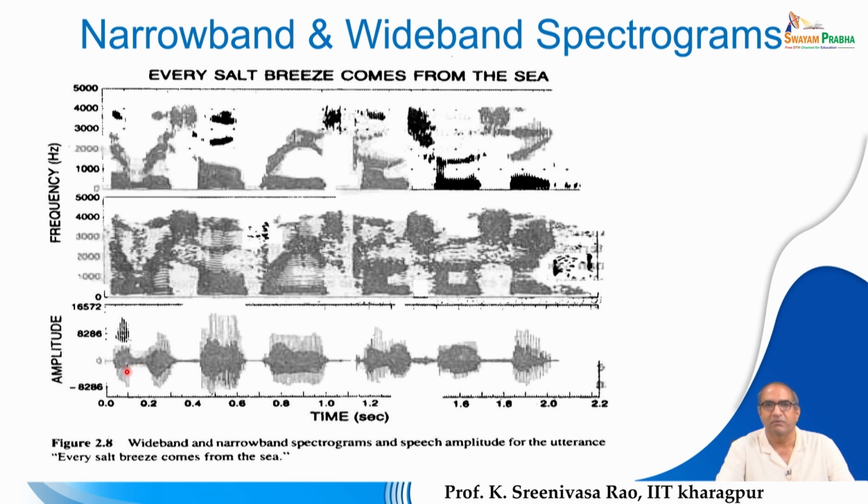So it's not wise to take a Fourier transform for the entire signal. If you do, you will get the frequency components corresponding to the entire signal. You don't see what the frequency components are for different sound units; you only see the resultant of all the sound units together. Since it is a non-stationary signal, we can't take the Fourier transform directly. The Fourier transform has to be applied on a stationary signal.